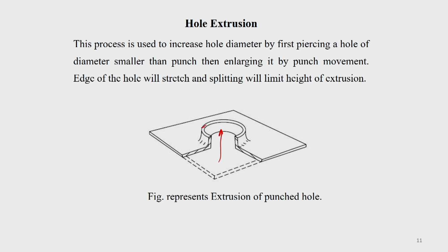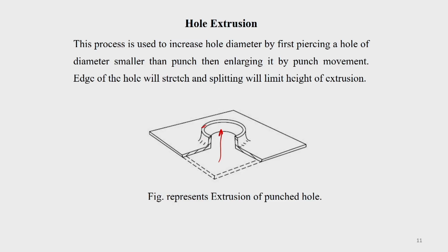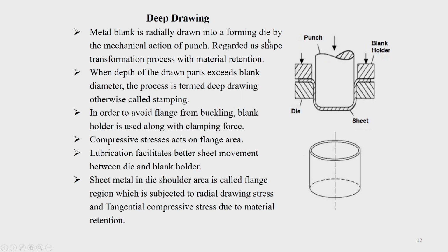So, one should know the formability behavior of the material, its ductility, and other R ratios and R values. Once you know that, you will be able to tell how much it can stretch and how much this hole can be extruded. If it is too much, there will be cracks. Okay. So, the hole will stretch and splitting will limit the height of extrusion.